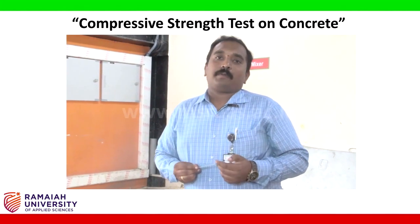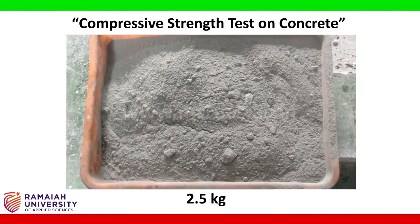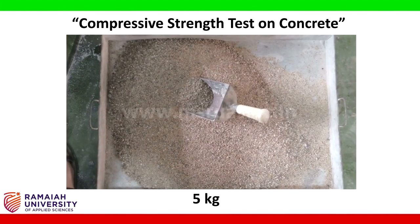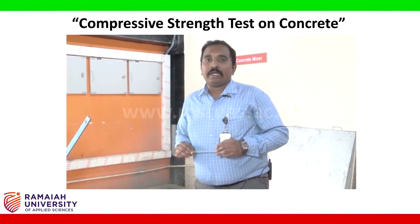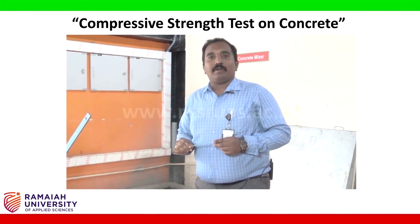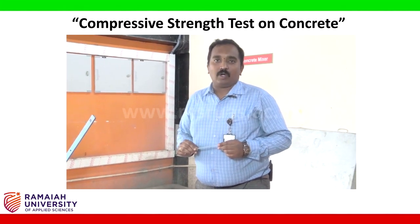The second step is preparation of the mix. As of now, we've taken 2.5 kg of cement, 5 kg of fine aggregate and 7.5 kg of coarse aggregate, which comes to a ratio of 1:2:3. We generally do it for M20 grade concrete. For the first trial, I am considering the water cement ratio as 0.4. We start mixing the concrete.